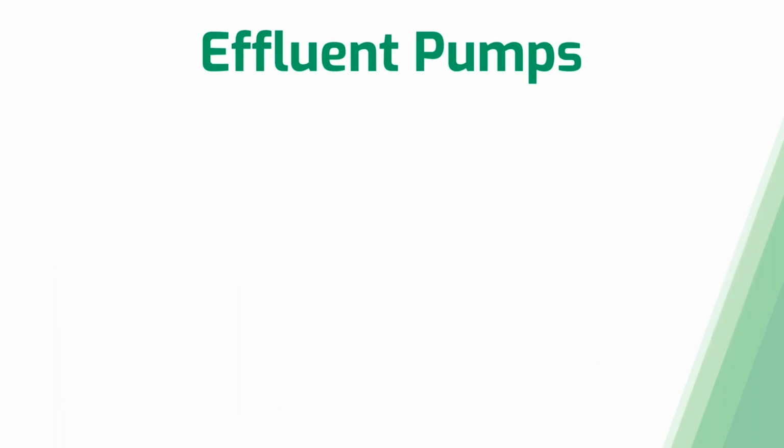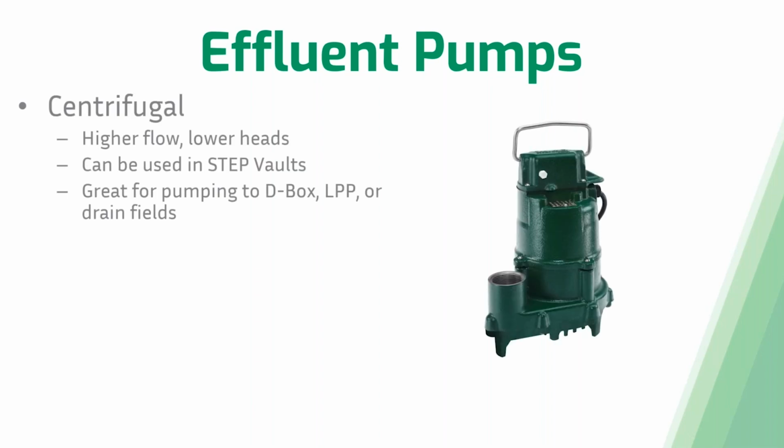So now let's discuss effluent pumps. So effluent pumps, again, they're primarily going to be pumping liquid wastewater. They should not be handling any sort of solids. These pumps put out high flow but lower heads, just like those non-clog sewage pumps. And these pumps can be used in step vaults. Typically, you're going to use them in a simplex arrangement in the step vault.